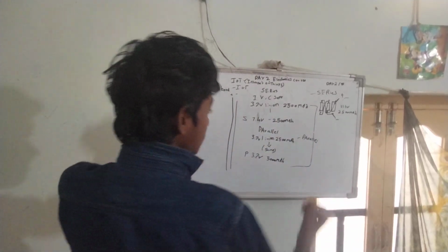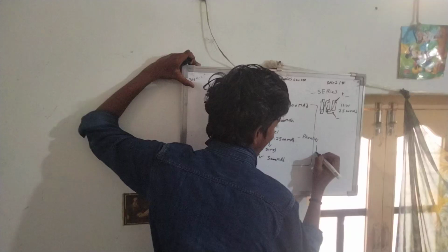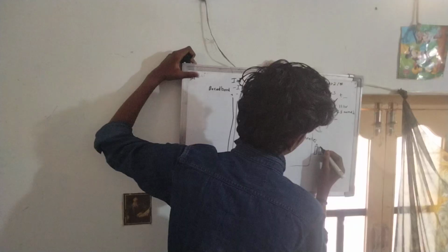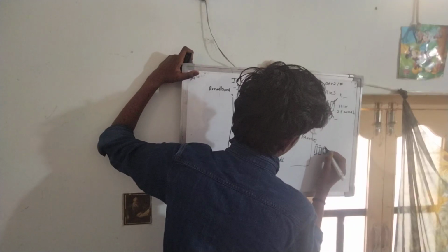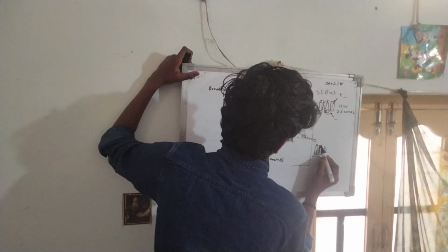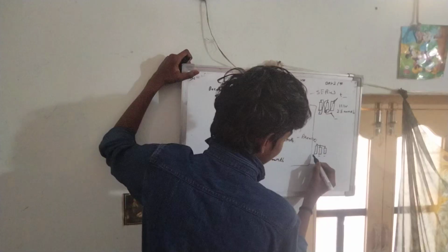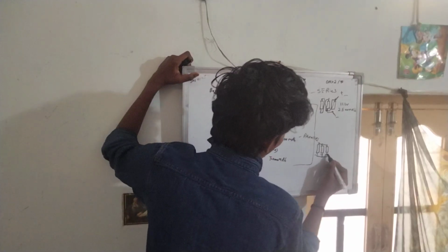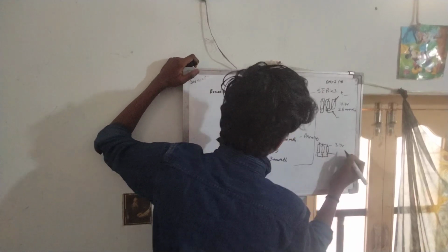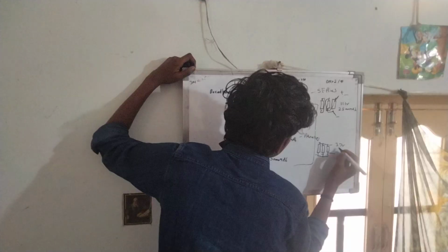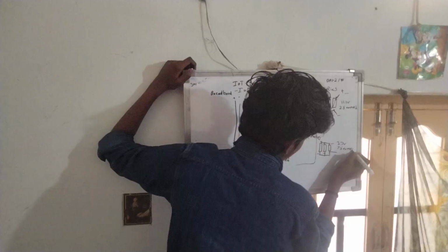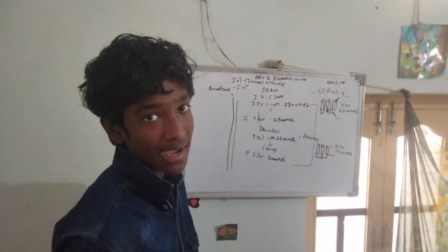Okay, now what is parallel connection? A parallel connection is very simple. Now we have the same 3 lithium ion batteries of 3.7 volts. We make it like this. Then we connect plus to plus, plus to plus, all the pluses together and all the negatives together. Now we get 2 ends. It gives 3.7 volts, but the capacity it can give will be 7500 mAh. This is the difference between series and parallel connection.